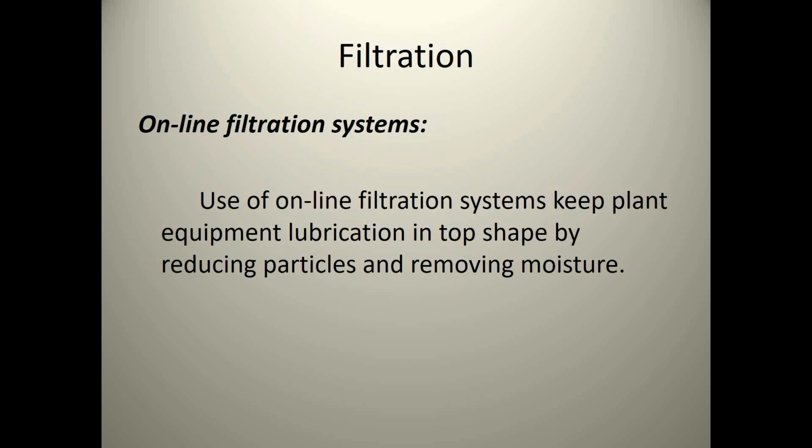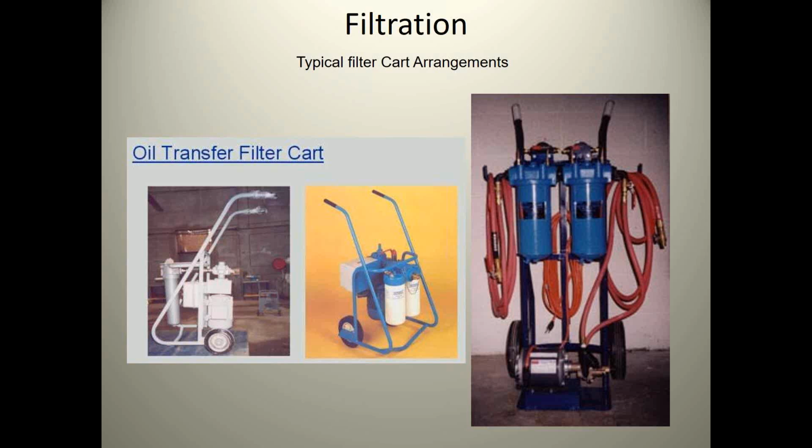With online filtration systems, a lot of times we can't change the filter in our hydraulic unit, so we need to buy a filter cart that we can move around our plant, and we did this a lot at the facilities I come from. I have a lot of customers that have filter carts. We take it up to a hydraulic unit, hook onto the bottom of the hydraulic unit, circulate through the filter cart, and put it right back in the top. By doing this, we can filter our oils down to real low levels.